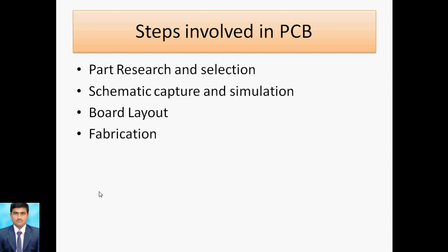So it can create a schematic for the PCB layout, then create a setup for the PCB, link the schematic to the PCB, define the board size and layer stack, then place the components, insert the drills and route the traces, and finally the component.